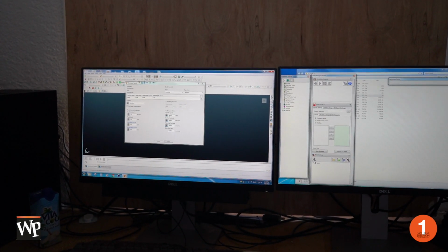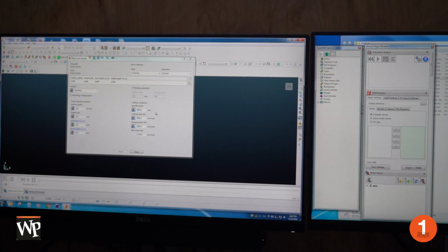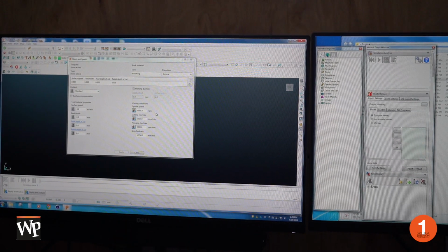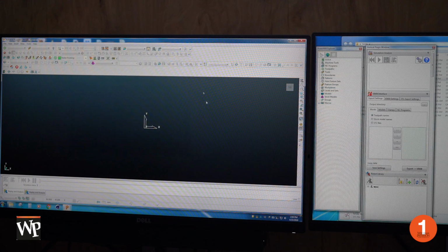Okay. Our spindle speed we have at 6,000 RPM, and that's determined by our tools. When tools are made, they have a certain balance that lists the optimal range. So our tools are in a tool holder, so we're already set on that. Our feed rate is going to be 18,000 millimeters per minute. Plunging feed rate 3,000 millimeters per minute. And our skim 12,750. Okay, so we're going to close that because that's set.